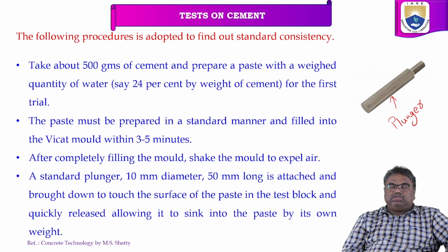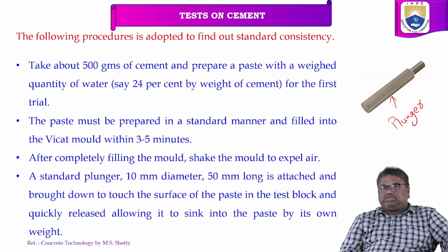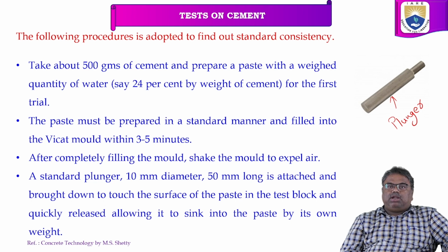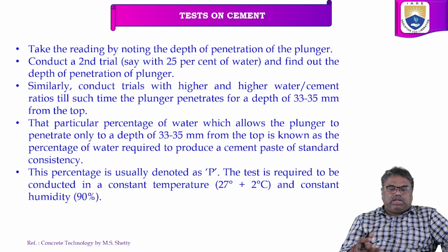So you have to quickly release the plunger and allow it to sink into the paste by its own weight. Take the reading, note down how much penetration has happened, and conduct the second trial. Use 25% of water and find out the depth of penetration.